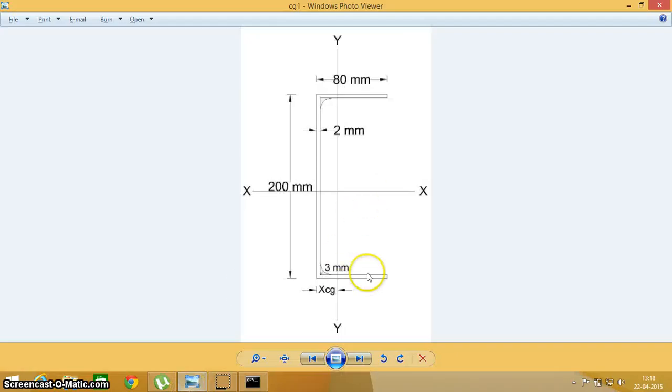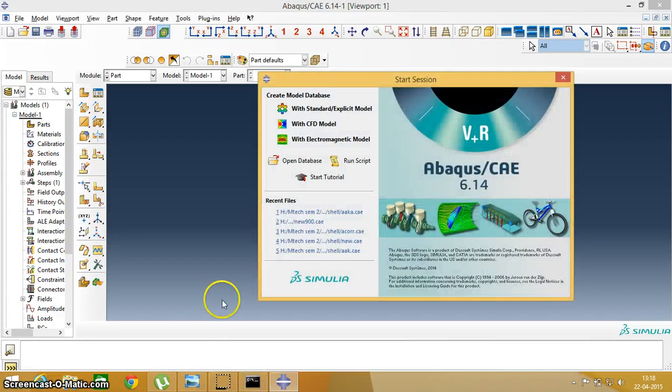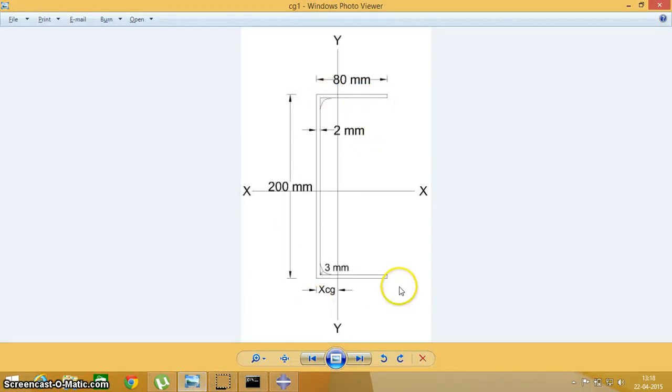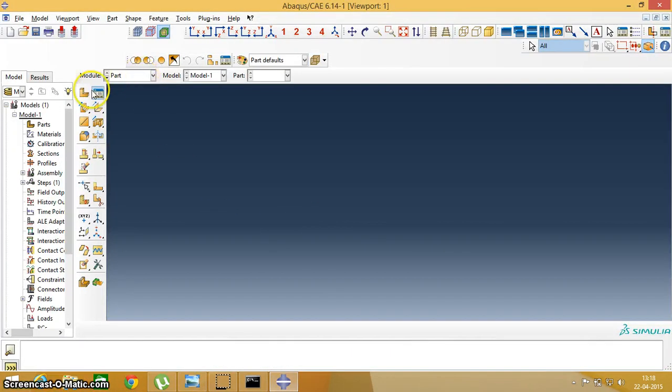This will take a time. So, here this is the section with 900 length. So, we have to mention here the coordinates. Here will be 80, 0, here 0, 0, here 0, 200, here 80, 200. So either if you take the midline of this section and thickness is 2 mm, or take outer distance. Taking midline or center line of this section is better. So I will take the outer part.